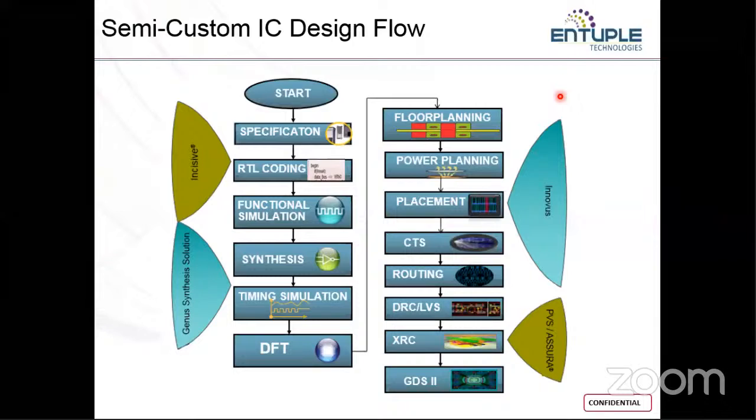So that is to include clock signals to your design. We go for a process called clock tree synthesis, and you have certain algorithms that will be working in the background in your Cadence tool. Okay, so H tree algorithm, etc., or basic tree diagram algorithm, that you can make use of for clock tree synthesis. And once that is done, you'll be going into the routing process.